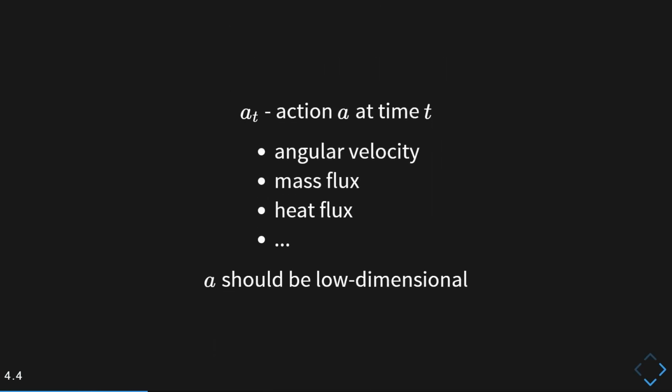The second thing is the action. So the action is how you actually modify your simulation, your means to actually achieve your control goal. That can be, again, that you rotate some part, that you inject some mass somewhere, or that you inject a heat flux somewhere. And for the action, of course, the same is true. You want to get away with as little actuation as possible.